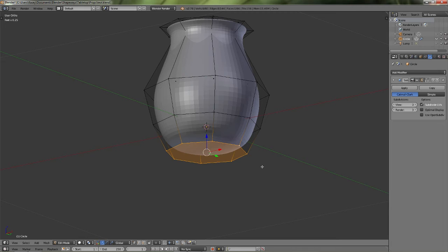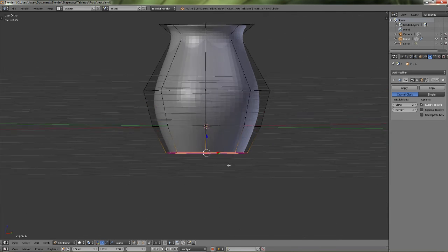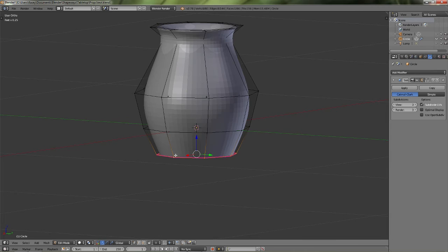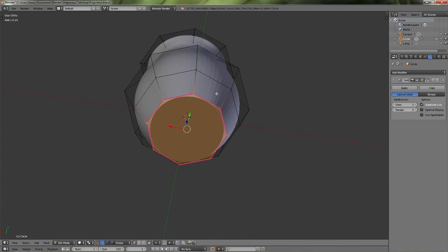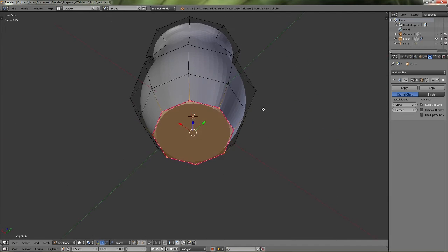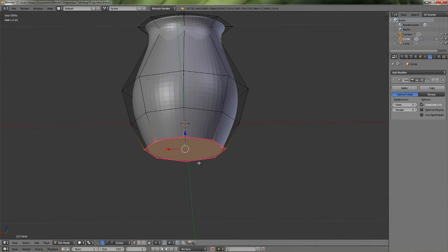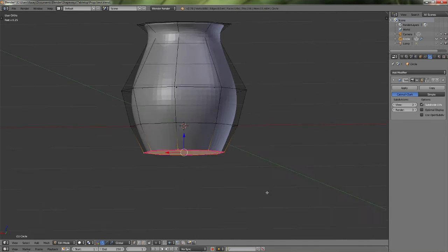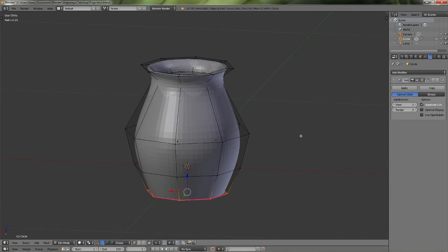So what you want to do to get a sharp edge, hold Shift and hit E, and it comes up like that little size arrow does, and just pull that all the way out, and now you have a flat bottom with a sharp edge. Shift E to sharpen any edge for you, and that will work beautifully. And now it has a flat edge. You don't have to worry about printing this out and it falling right over. So you don't want that.